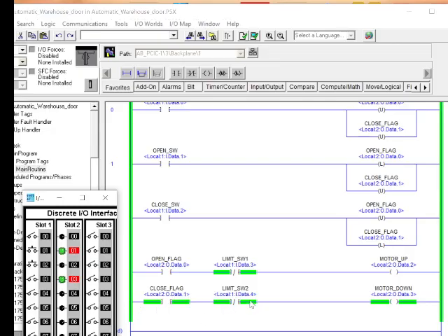Then the limit switch will be normally closed as long as you haven't reached the lowest point. Then our motor will be on till we reach there, and let's say we reach there. The limit switch is at the point where it's going to change position. That is 4.